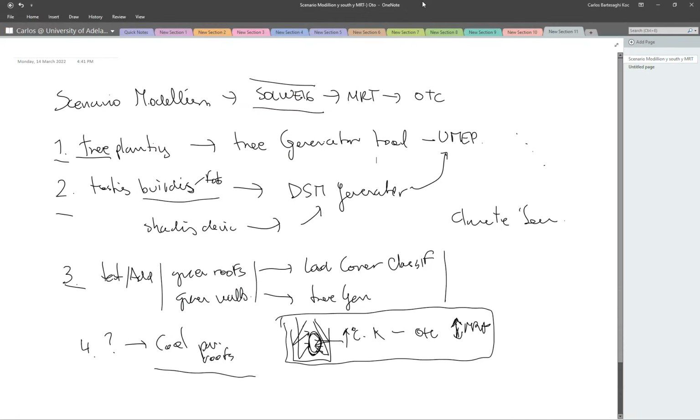By trunk height, I assume you understand, well, this is the ground, this is the trunk, and this is the height of the canopy. Here you can assign a value, for example, 4 meters above the ground level, and then the whole tree will be 8 meters, so you will have 4 on the top of the canopy.